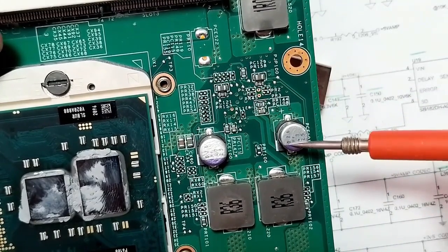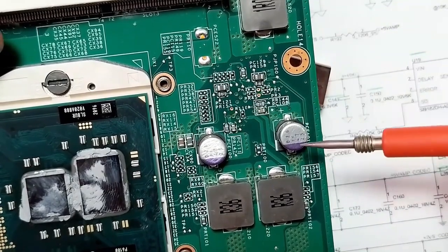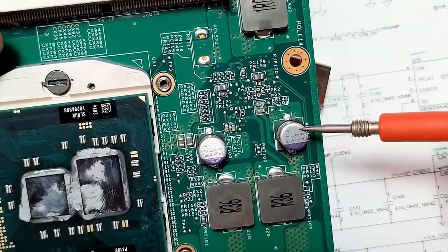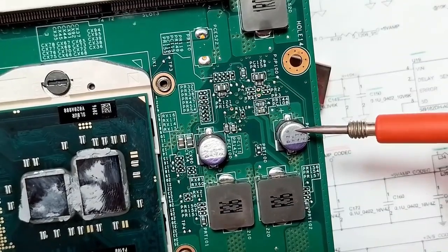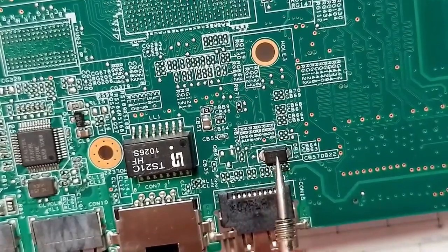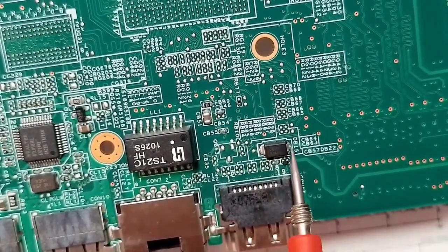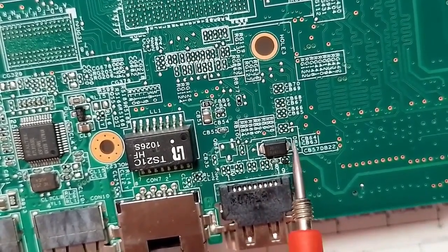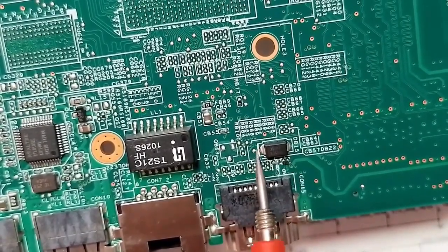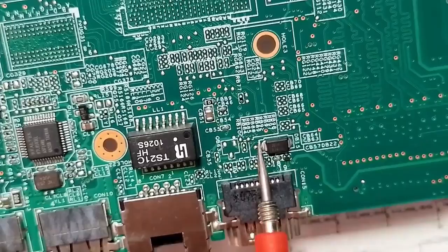Okay, so this color here means minus, and here we have plus. So these capacitors also are polarized capacitors. So coils, this is a diode, as you can see. Here we have the cathode, and here we have the anode. We have here D, as you can see. So this white mark means this is the cathode, or the negative terminal.